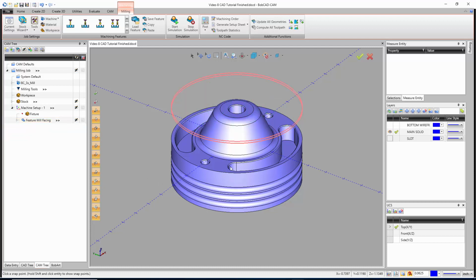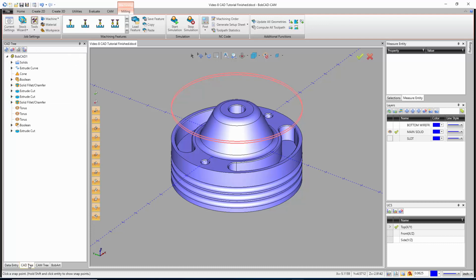And the next thing we're going to do is we're going to take off the material down to this floor. So to do that, the easiest way is to use a 3-axis toolpath. Now it all depends on how we want this to work, but if I don't want my 3-axis toolpath to cut inside of this area, then we would actually go in and modify it so it doesn't cut in there. We would actually put covers over that, or in our case, we could actually right-click on the extrusion that we made when we did it, which is these guys here, and say suppress those. And what that's going to do is it's going to hide them completely. And as long as we pick our geometry when these are turned off, the tool won't try and machine into those. So that's what we'll do.